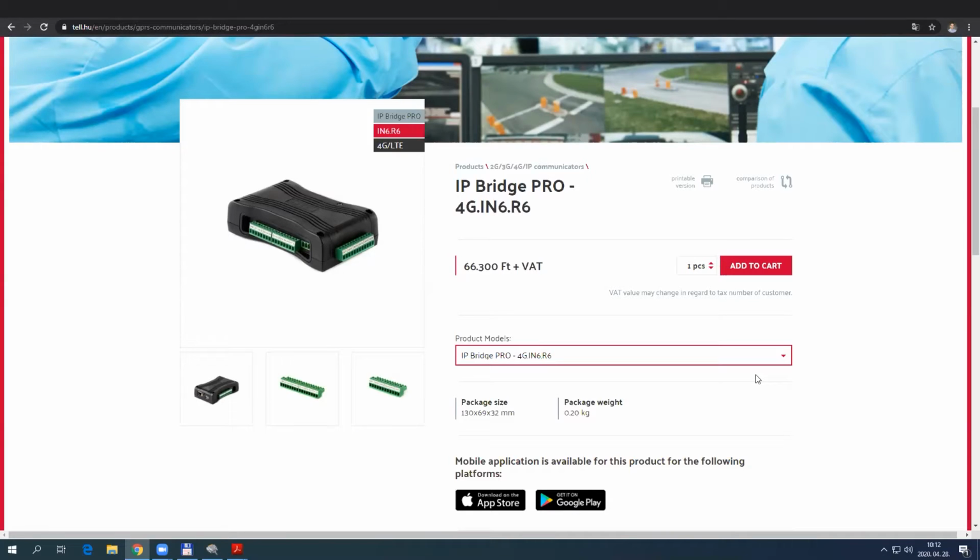So you can use the device as an IP communicator for burglar alarm and fire alarm systems, or even as an IP-based control module with remote control options for automated remote control over the internet between equipments using dry contacts. The transparent serial port available on the device enables using the device as an interface for remote communication between equipments provided with an RS-232 interface.